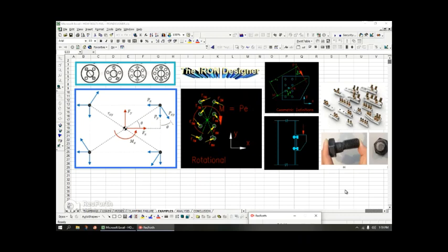And the one below that, it's just showing a simple vertical load that you would think is only a shear load, but there's actually moments created, and the engineer needs to study if the reaction moments are greater about the upper bolt or greater about the lower bolt. And I'm not getting into that analysis in this video. I'm going to stick here with just bolt failure modes.